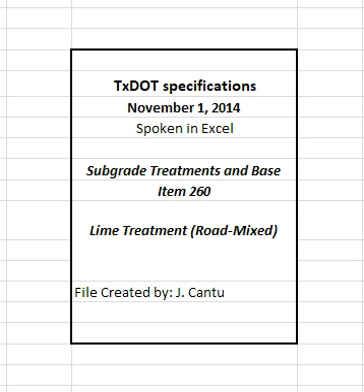Untreated material PI greater than 35 with a curing of 5 days. 1. Subject to the approval of the engineer. Proof rolling may be required as an indicator of adequate curing.